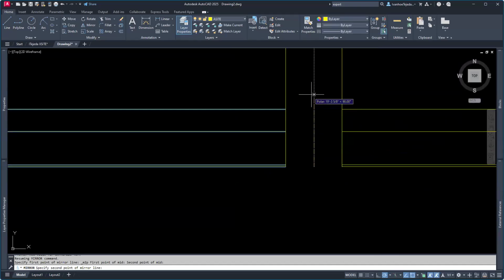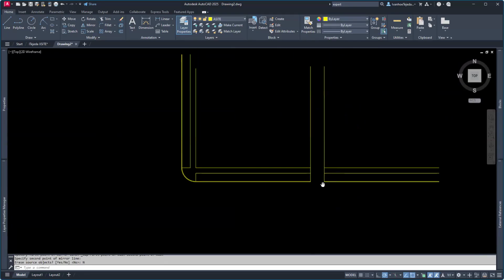And I just click up here, or I click down here and click no, and I have the line work. Now, I don't need to finish it. I could later, but really all we're going to be seeing is this here. So I'm going to focus on this area. I just wanted to show you how to mirror using that mirror between 2 points, midpoint between 2 points.